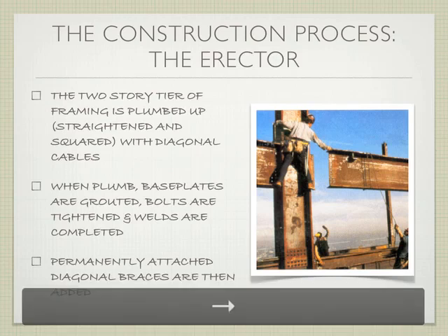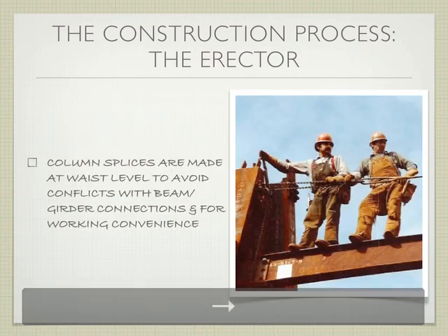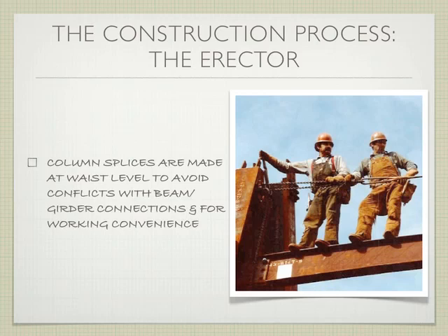Then we move up in the whole building. The columns are always made to join roughly at about waist high. So if we're spanning 2 stories, the column is really 2.5 stories, because we need to get it above waist height. The reason we do that is that it's obviously easier to work with, but the other factor is it never interferes with one of the floor joints.